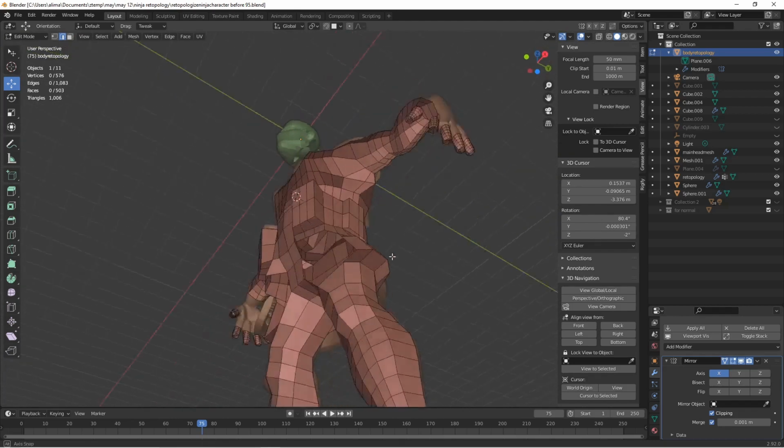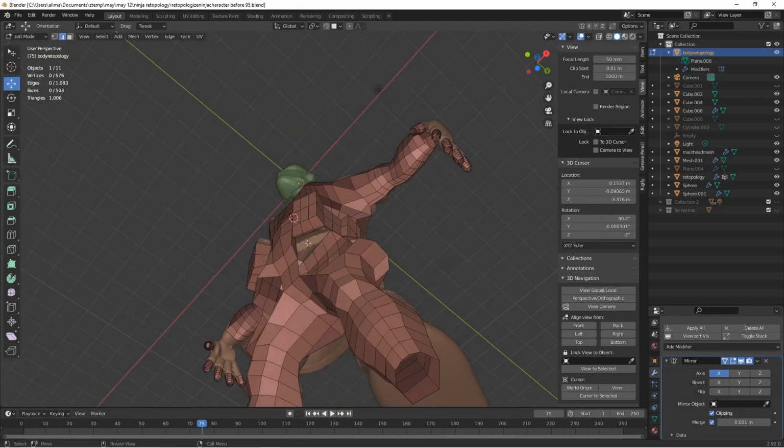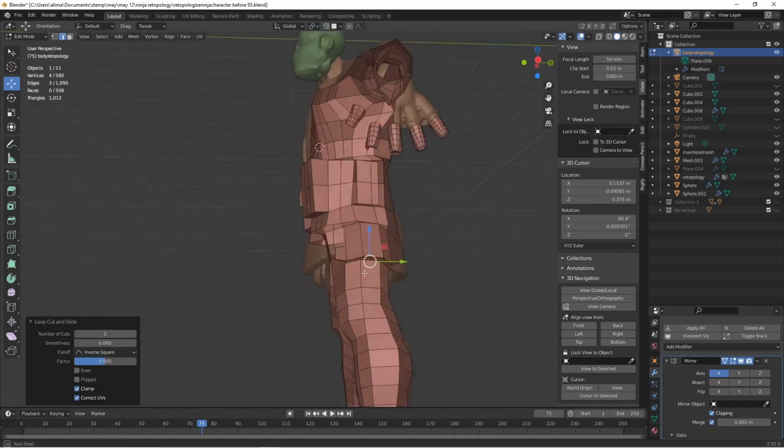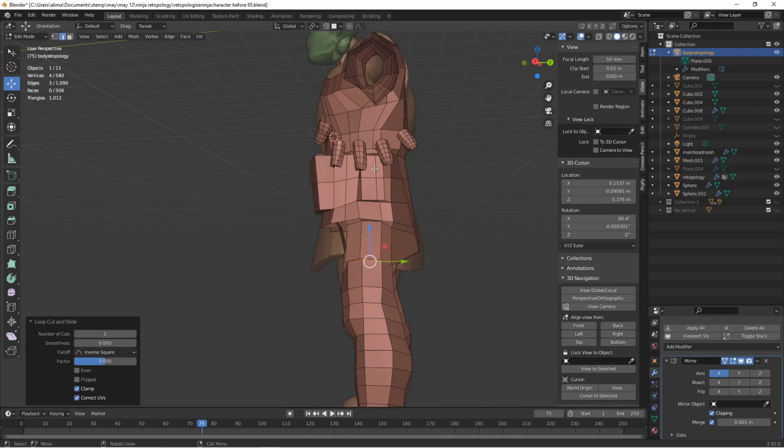Okay, we're going to put a loop here to match up with that there. I can see that's difficult to see. We're going to hold Control, press R, left click once, left click a second time to lock that in. I want to have this show up, but have this not show. I'm going to hold Alt, press A to deselect. We can do that by holding Alt and then pressing B.